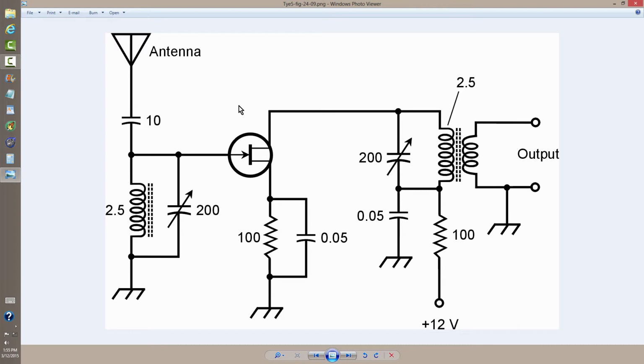But the question of where to put that probe, again with a series blocking capacitor to prevent DC getting in the way of the performance of the oscilloscope, the point to connect that probe for the input would be here, assuming your oscilloscope is sensitive enough to detect that signal, or here. I'd connect it here and then adjust both of these tank circuits together until you obtained the greatest possible signal amplitude here. Then you would know that both of these tank circuits were tuned to resonance. You'd know that in practice they actually were.